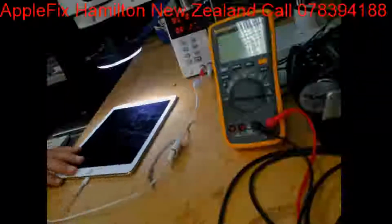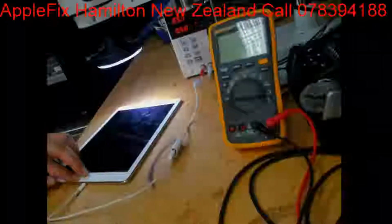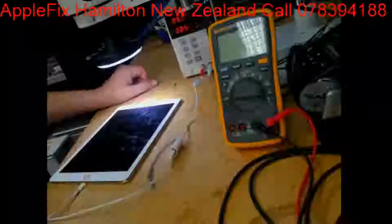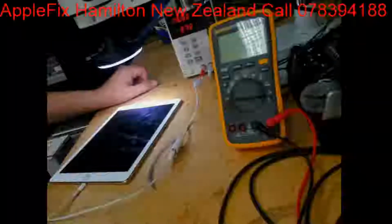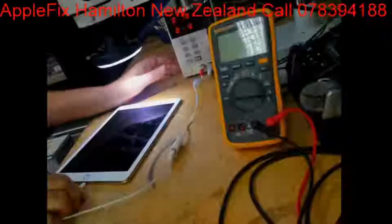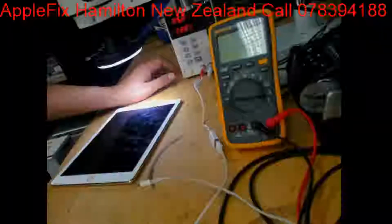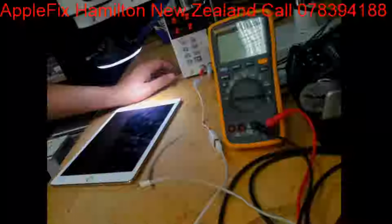The power lines are where you put the power plug here, and then these lines go to a component called the power IC, U2 IC, and the voltage and the current are transmitted from there. So in this case I will turn it off, and I will directly go to the schematic diagram on power lines. So these are our power areas.